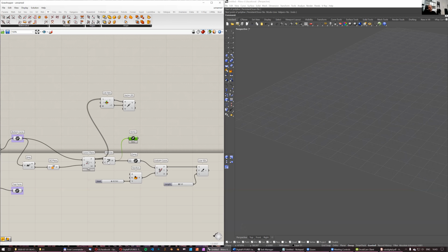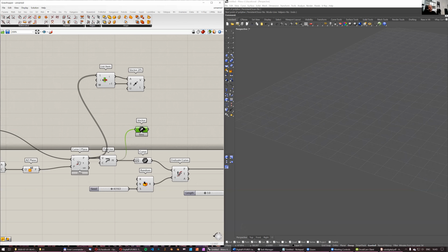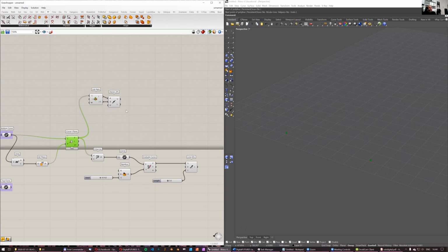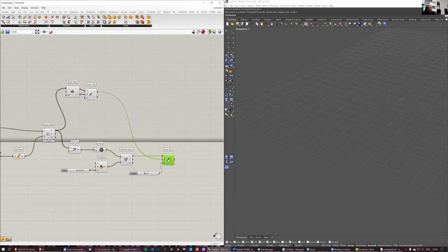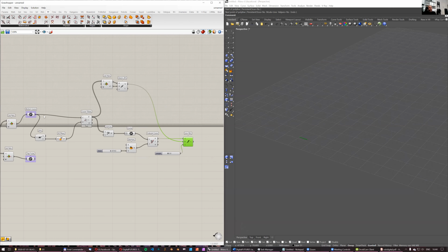A straight line can convert to a vector by defining the vector from the start point to the end point of the line, but that's way too implicit. This is way more explicit, way more clear. So this is the direction of the line. And you see now I've got a 3 millimeters long line that is part of the curve that I defined here. So basically that's the bottom edge of the leg.